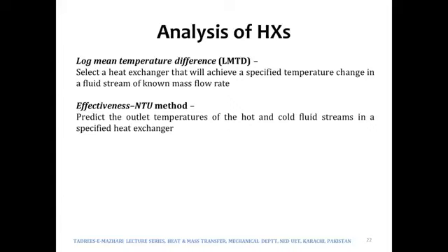One is called the log mean temperature difference method, LMTD, and the other one is called the Effectiveness-NTU method, or Epsilon-NTU method. NTU refers to number of transfer units. The LMTD method, or rather, the log mean temperature difference method, is used to select a heat exchanger.